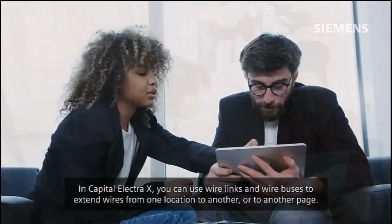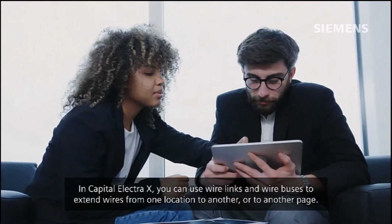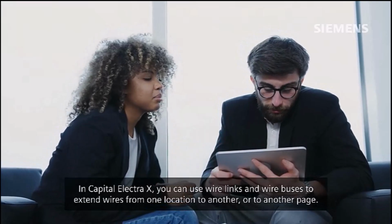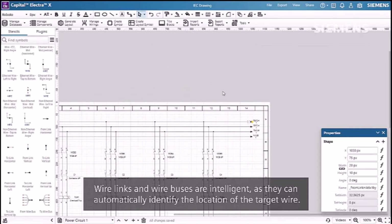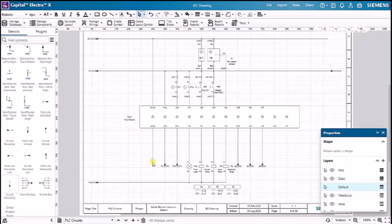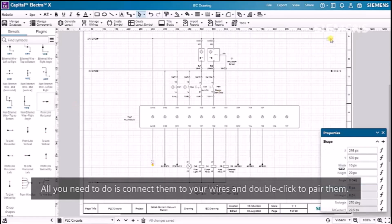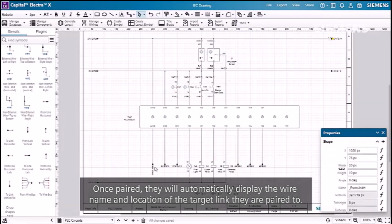In Capital Electra X, you can use wire links and wire buses to extend wires from one location to another or to another page. Wire links and wire buses are intelligent as they can automatically identify the location of the target wire. All you need to do is connect them to your wires and double click to pair them. Once paired, they will automatically display the wire name and location of the target link they are linked to. Double-click on the paired wires to jump to the target link.